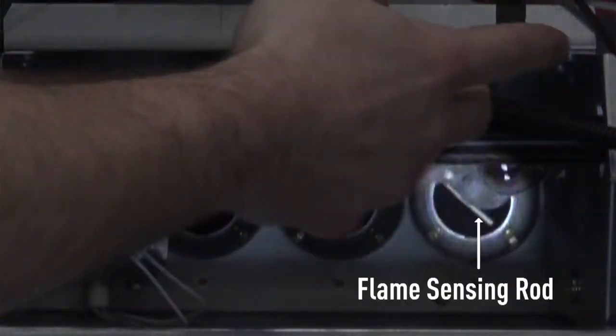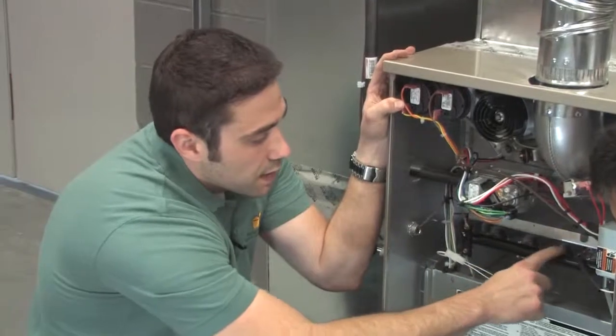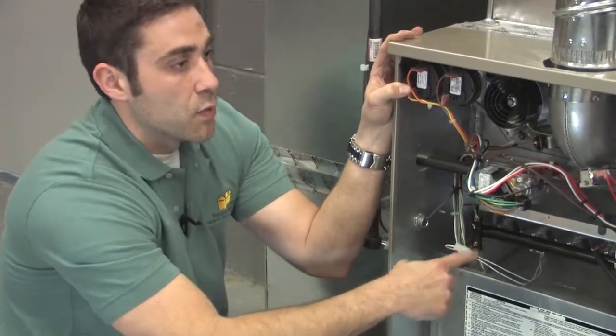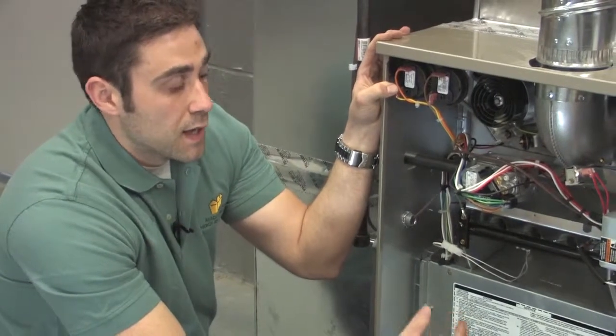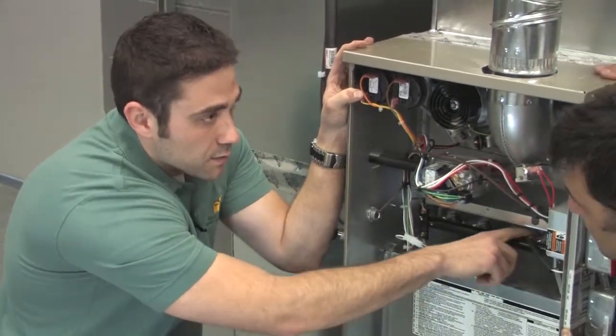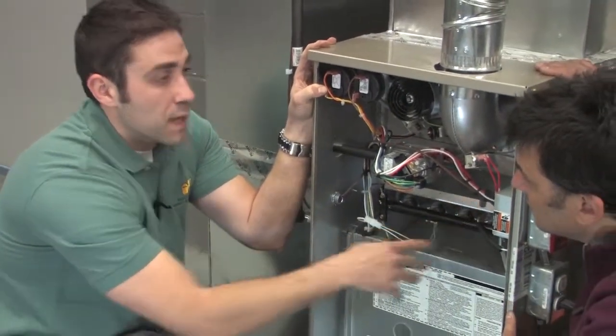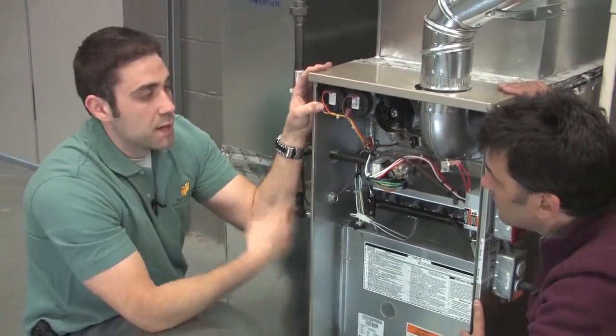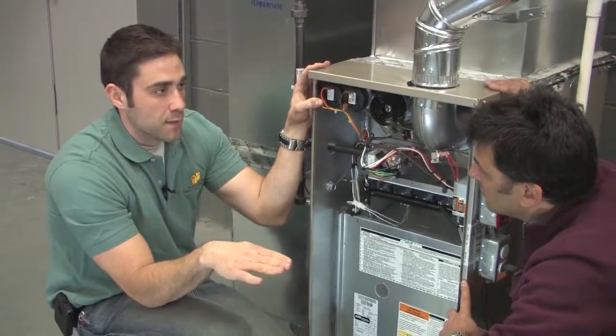And what this does is that it ensures that all the burners are lit. So every burner lights up, and if this burner senses flame, then it knows that every single other one lit up before it, and it's safe to keep the furnace on. If this one doesn't sense heat, the flame sensing rod doesn't sense heat in the last burner, it shuts the system off. And then it goes through a retry. And it'll try a couple times, and then it'll go into lockout, and it won't run the system anymore because